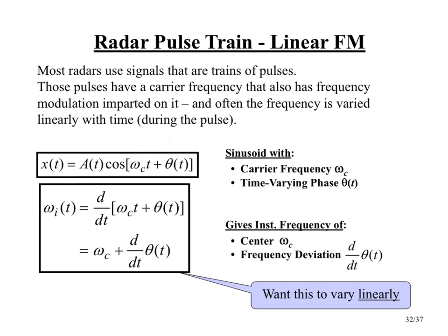And that is our instantaneous phase. Since frequency is the rate of phase change, radians per second is our unit for frequency. Just like we have position in meters, and then velocity in meters per second. If we've got a time-changing position, we take the derivative to get the velocity. If we've got a time-changing phase, we take the derivative to get the instantaneous frequency.